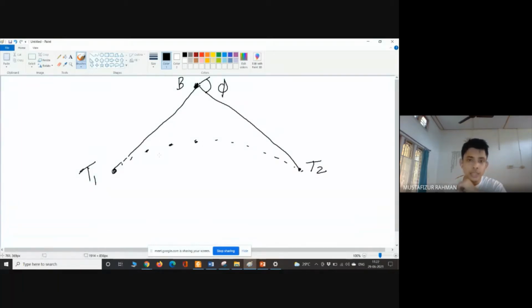Now how will the points on the curve be selected? Okay, for that we can find out some deflection angles. So deflection angles from where? From this line, okay? Depending upon the chord length. So what we'll do, we have this total length of the curve, which we will divide suitably. Okay, 20 meter, 30 meter, 50 meter, something like that. We will divide the length of the entire circular curve into suitable divisions, and there we will find out deflection angles. Say for example 20 meter.